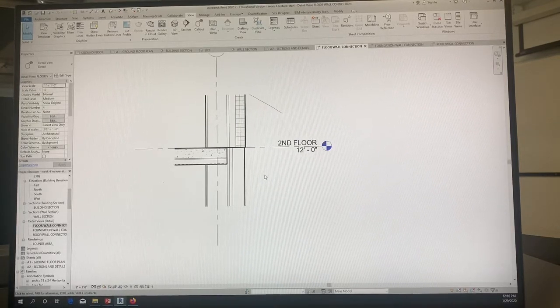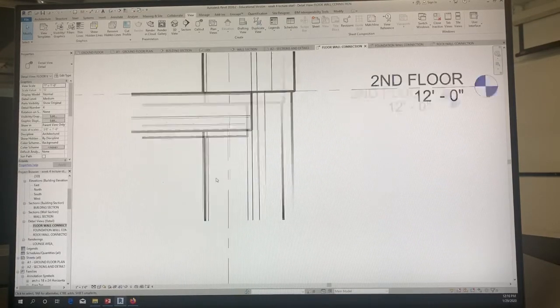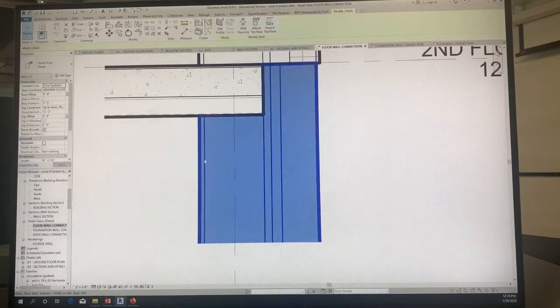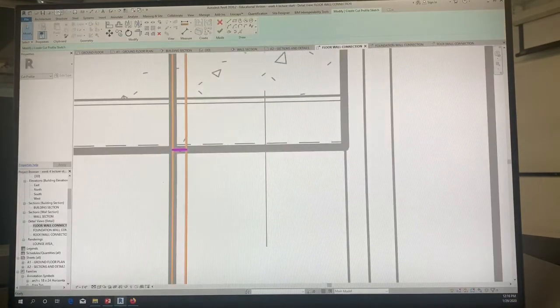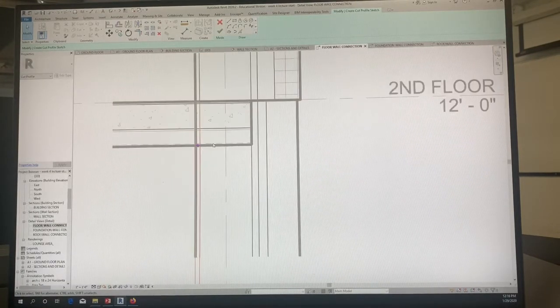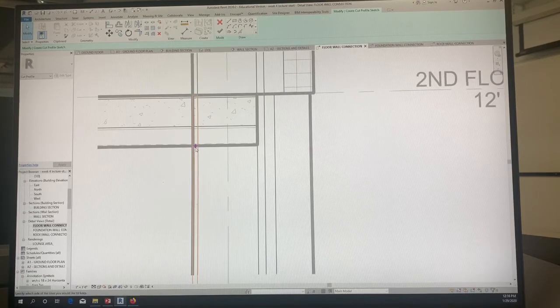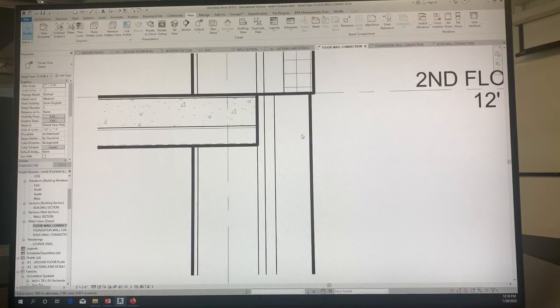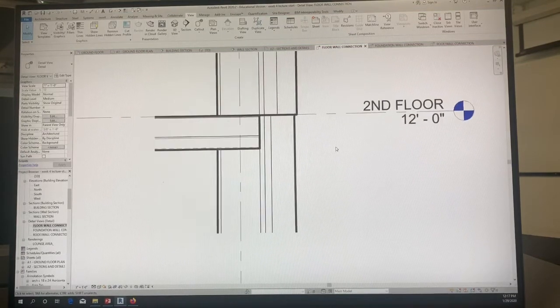Sorry. I should show you that, because there's actually an arrow when you cut it. So watch. I'm gonna undo my cut here. Do you see that arrow right there? Sorry, my apologies. I didn't show you that. If your arrow is pointing upwards like that, you're gonna keep this. If your arrow, which in our case should be pointing downwards, then you'll keep that. So again, pick that arrow, making sure it's pointing downwards, before you finish. That'll tell you which side you want to keep.